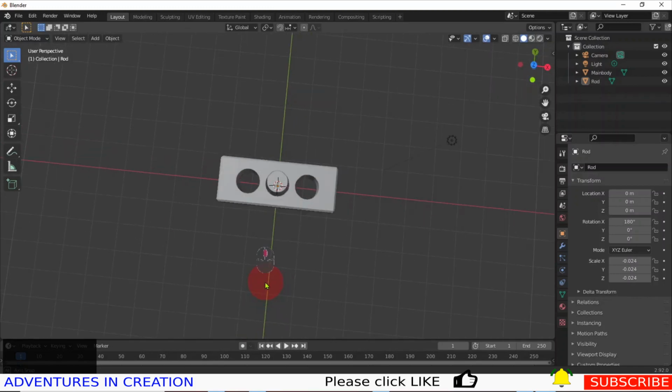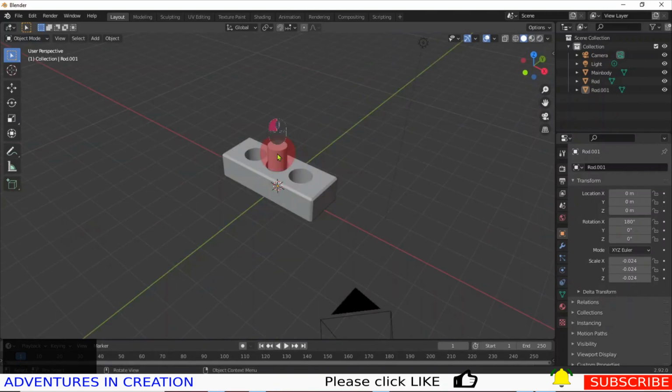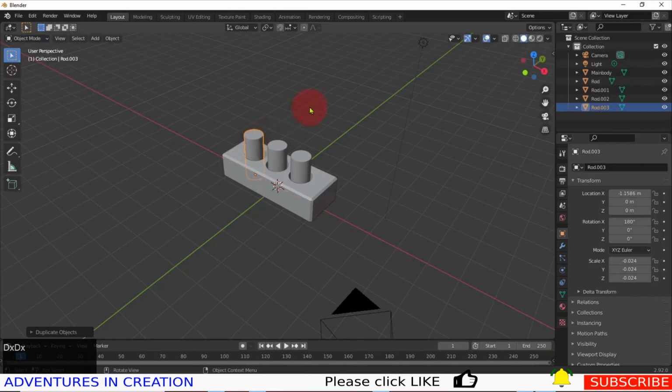And it's roughly the right dimension. And okay, so I'm going to select that rod, Shift D and X, and that says I want to duplicate it in the X direction. And I'm going to go back to the middle one, Shift D, X, and move that in the other direction.